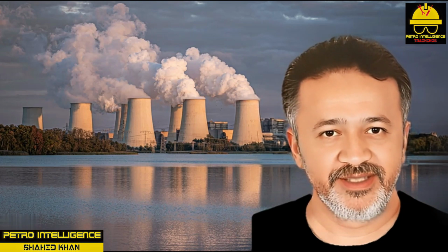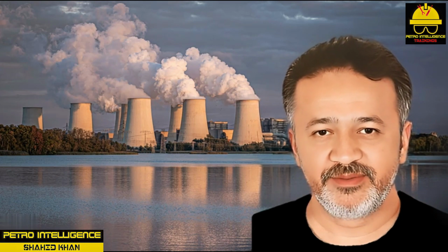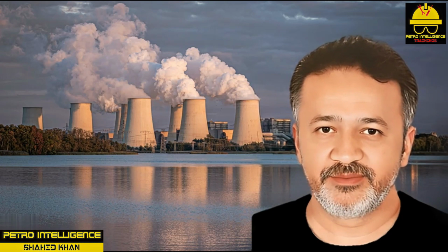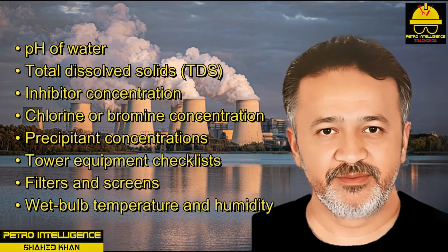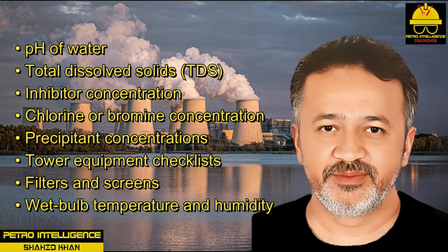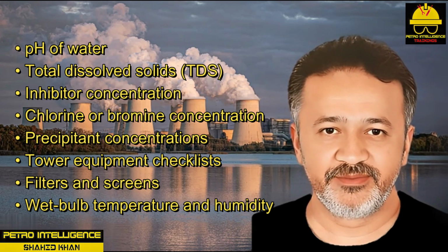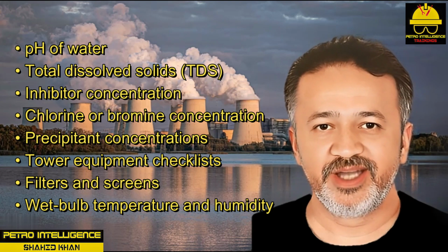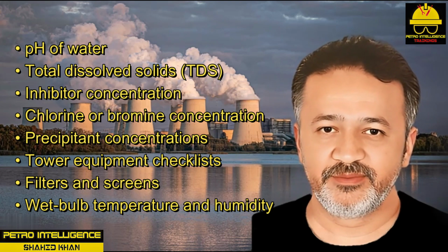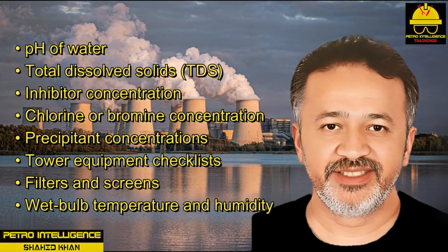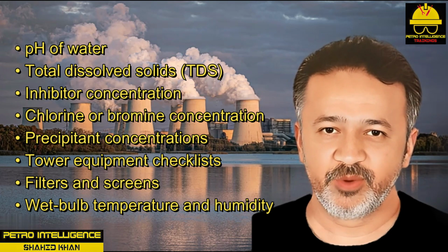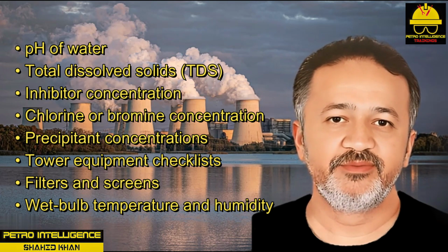All of these problems and solutions require monitoring. Operators are responsible for testing and checking pH of water, total dissolved solids, TDS, inhibitor concentration, chlorine or bromine concentration, precipitant concentrations, tower equipment checklists, filters and screens, wet bulb temperature and humidity.